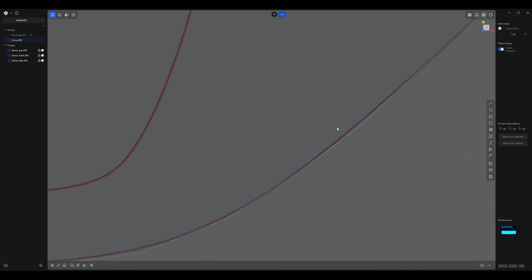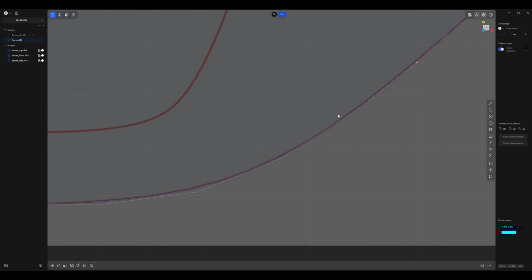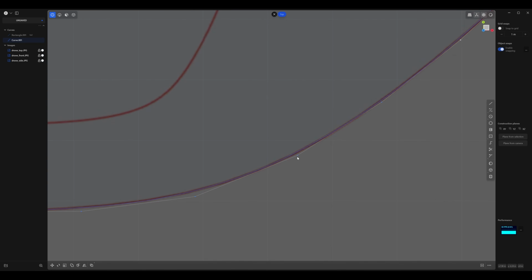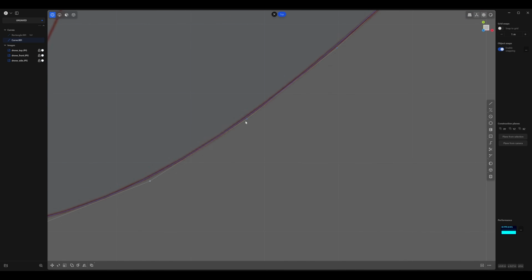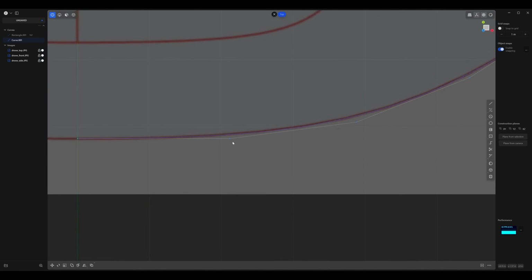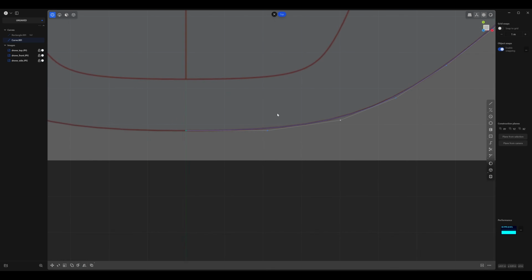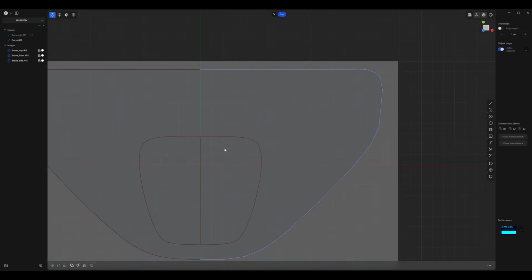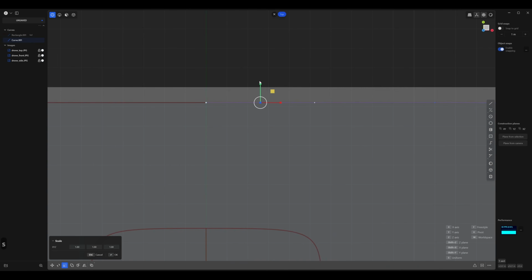And you can always change these as you go, but there's going to be a point where you start building surfaces, and these are the curves that you'll use to build them. That takes a little bit longer to kind of go backwards. So you just want to make sure you get these right in the beginning. I'm going to select these 2 points, press S, and scale them down, and press 0. They were already aligned, but I just want to show you that that's a way to make sure that they're aligned.